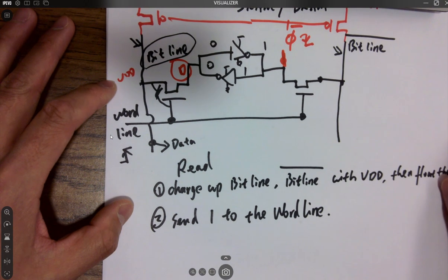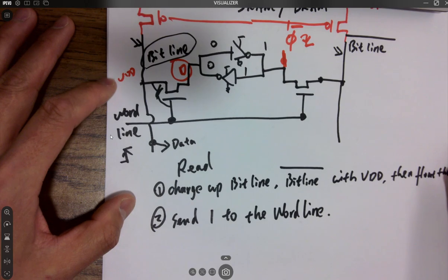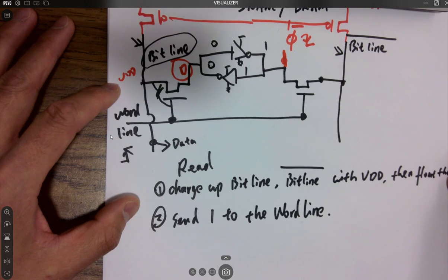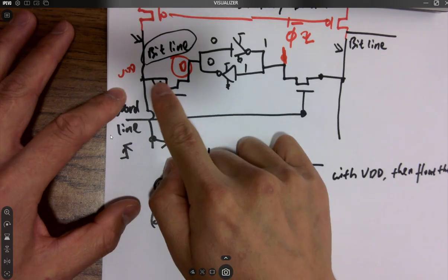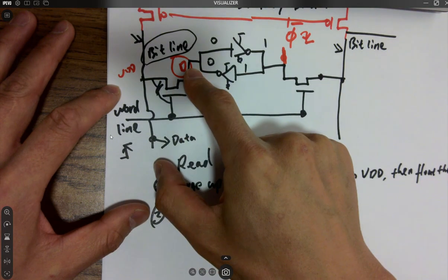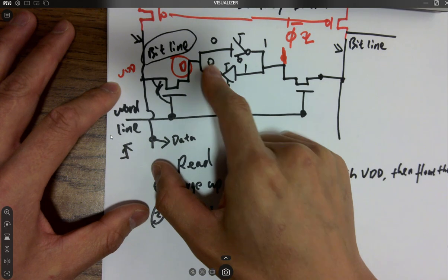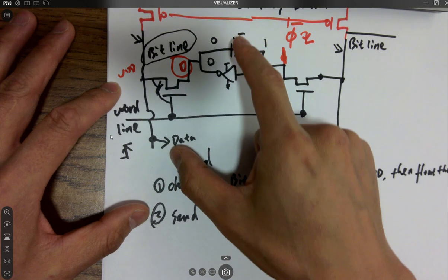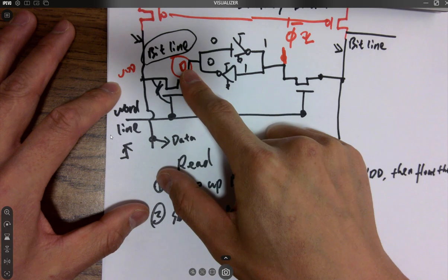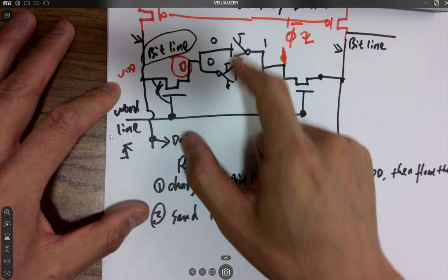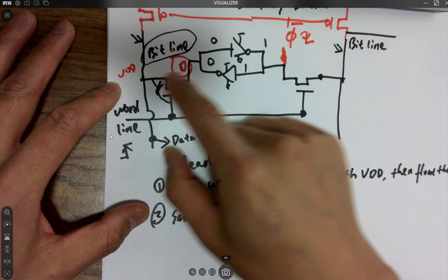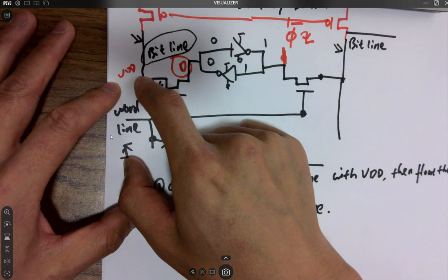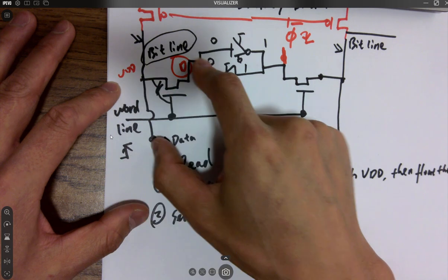That'll drop it, using the rising edge. VDD will go to 0. And then what's going to happen? Because this is 0, right, it's a strong 0. Connect to this guy or this guy? This 0 shorts to which ground? The bottom one, because this is the output. The output directly has a channel to ground, right? So the finite amount of charge here, the floating VDD, will be drained to the ground here, right?